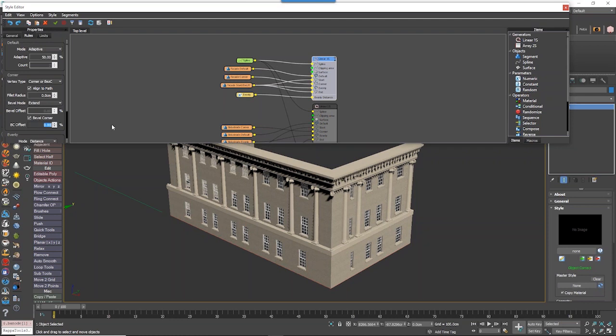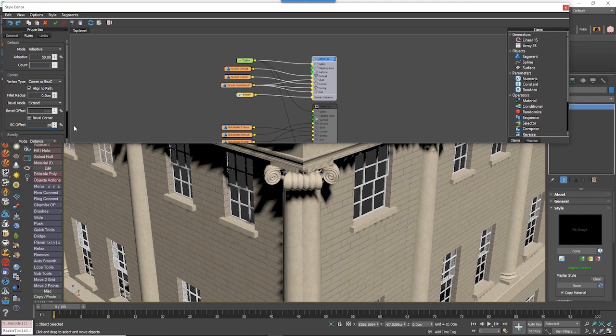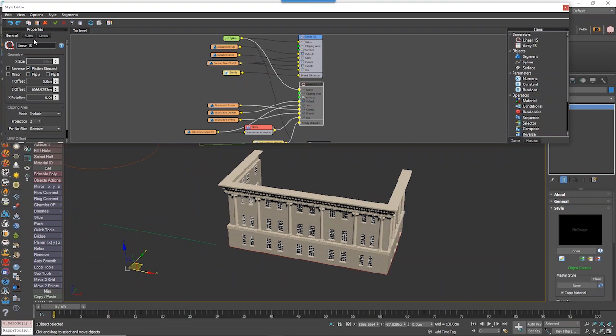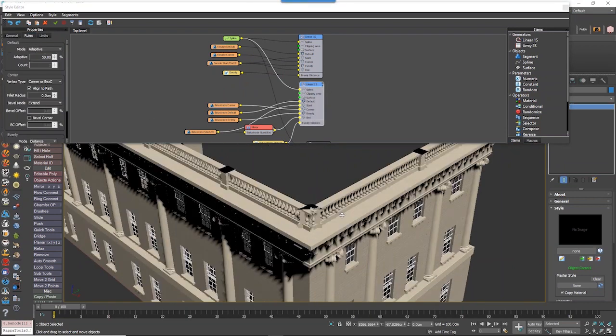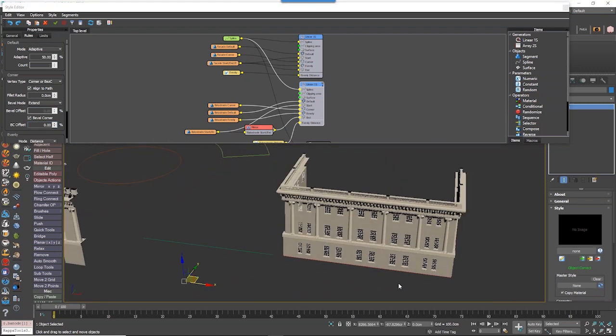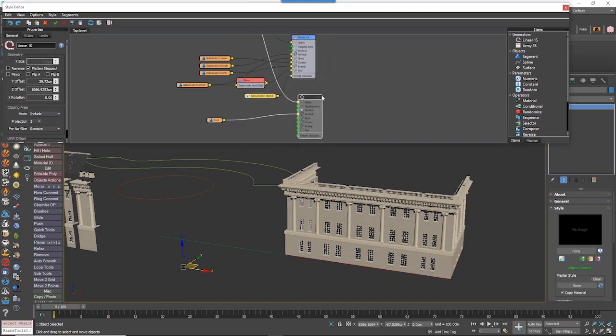And then you can change the offset of this to bring these sides close together, because you can see I've got this weird slice here where there's a pillar in the middle that's being sliced. So if I increase this value, it draws the corner together. That's too much. That seems a bit better. So now I've got my corners set up, and I just want to do that to this one too. So I'll just hit bevel corner, and well, that's okay actually. Okay, so there's a style done using 3 generators.